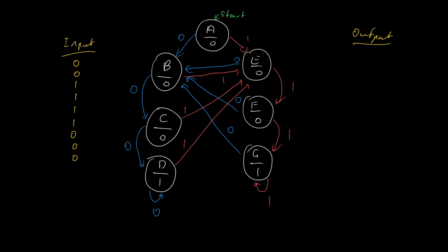Because it's a Moore finite state machine, each node has to have the current state and the output when in that state. And the number of bits in the output needs to be the same throughout. You can't have a variable number of outputs in a digital circuit.